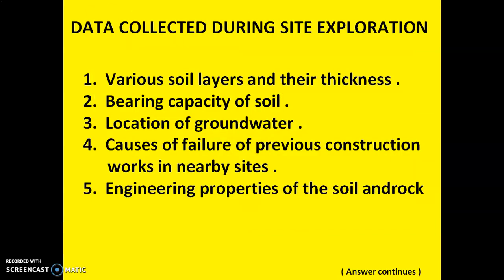The data that need to be collected during site exploration are various soil layers and their thicknesses, bearing capacity of the soil, location of groundwater, causes of failure of previous construction work in a nearby site, and very important, the engineering properties of the soil and rock.